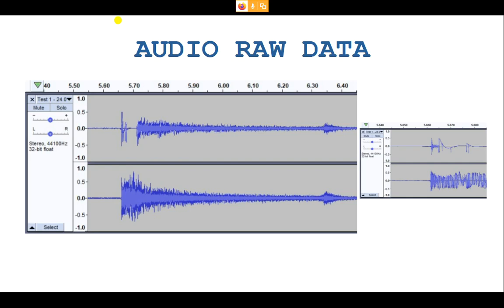Professionally, to do this as an experimental thing, in a laboratory, as a faculty or a researcher, what you can do is replace these microphones with transient pressure sensors and connect these to a data logger and track all the signals, and then you will be able to find where the pulse or shock happened, and the time between those two pulses exactly will tell you what is the shock speed.